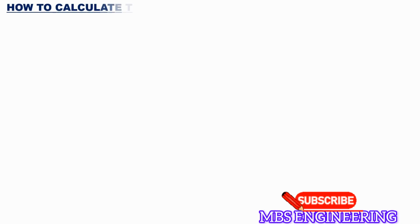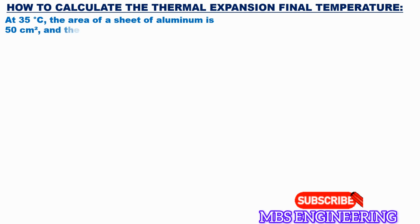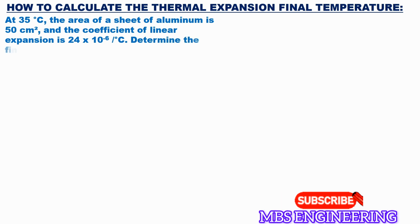Next, we will learn and understand how to calculate the thermal expansion final temperature. At 35 degrees Celsius, the area of a sheet of aluminium is 50 square centimeters, and the coefficient of linear expansion is 24 into 10 power minus 6 per degree Celsius. Determine the final temperature if the final area is 50.2 square centimeters.